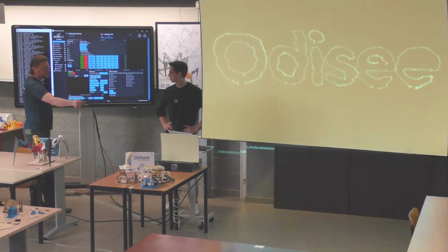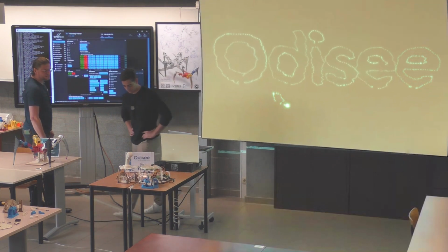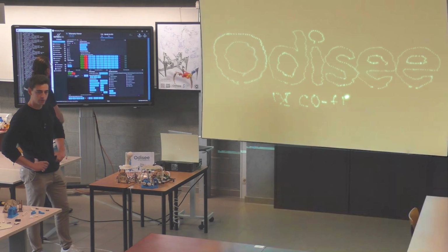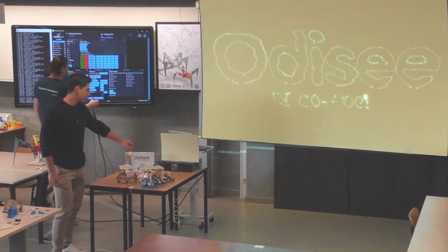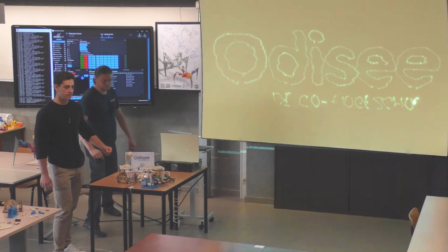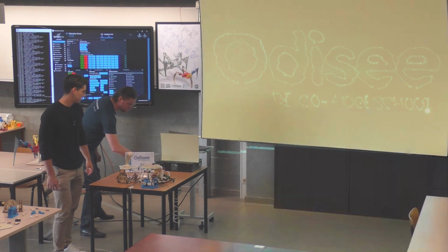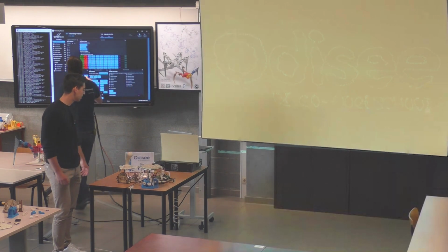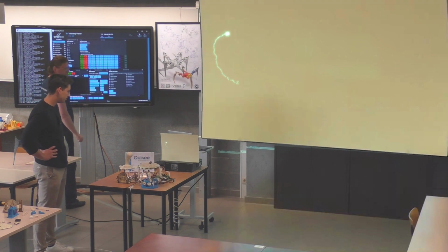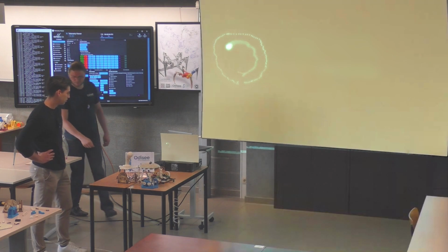Now we are showing the pulses, so you can see the actual amount of pulses that are in the code. There are little points being drawn, and every little point means one step of the animation. Between every point, we don't know where the servos go. That's why there's jitteriness. So this animation has, if I remember correctly, 1,600 steps, something like that. Every step is one little point you see here.